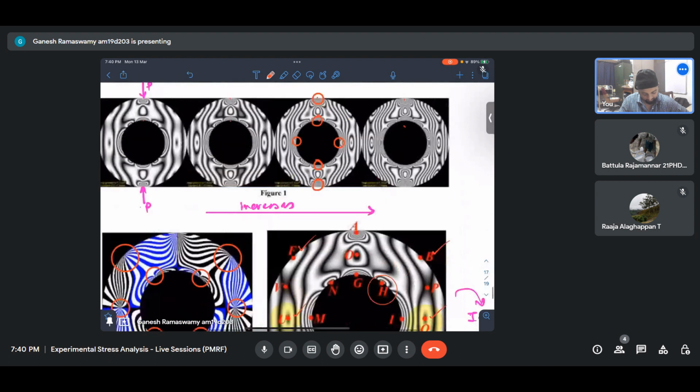So this we know is an isotropic point. These are singular points. The fringes come out from here and the fringe density increases. The point doesn't disappear because it's not a sink, it is an isotropic point. So the fringe density starts becoming very high. There are more number of fringes.